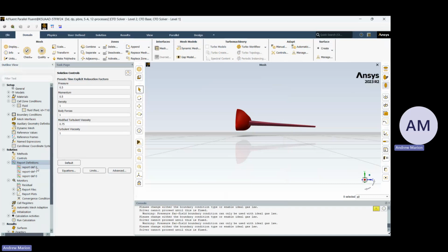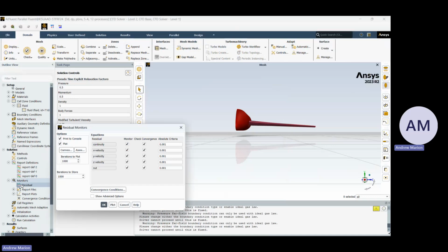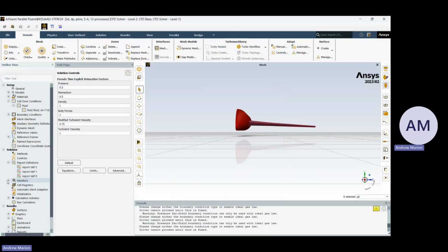There's capital L lift coefficient and lowercase l lift coefficient. If it's a capital L, they are giving you the value for the entire aircraft, including the body of the aircraft. If it's a lowercase l, it's just for the wing. And it's the same thing for drag. If it's a capital D drag, it's the drag for the entire aircraft. If it's a lowercase d drag, it's typically a drag for just the wing.